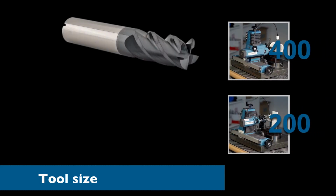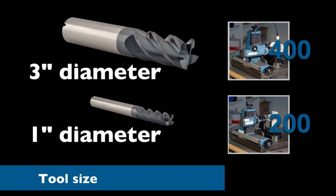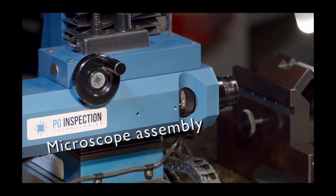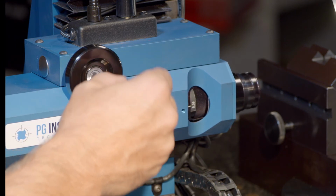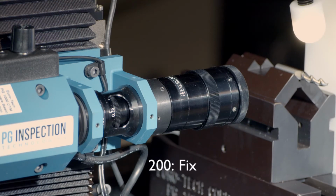The PG1000 400 can accommodate tools up to 3 inches in diameter. The PG1000 200 can inspect tools up to 1 inch in diameter. The difference in capacity is caused by a difference in design. The 400 models have a microscope assembly that is mounted horizontally on a linear bearing and controlled by a hand wheel. This additional travel allows the 400 to have a larger focal range. That's why it can handle tools up to 3 inches in diameter. The PG1000 200 microscope assembly is fixed. That helps it to reduce cost, but it also limits the focal range.